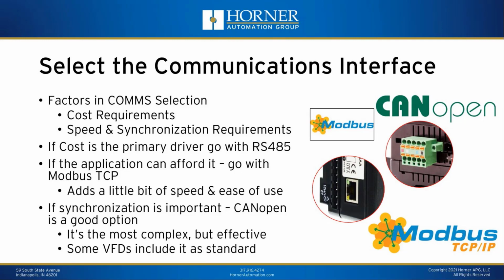Now, it certainly is more complex, and I'm not going to cover all the details of setting up CANopen with a drive here, but we absolutely have examples that we can share with you for doing that with a couple different drive manufacturers. So again, it is the most complex connection when compared with Modbus or Modbus RTU, but it does offer a level of synchronization that you're not going to find with those other two choices.